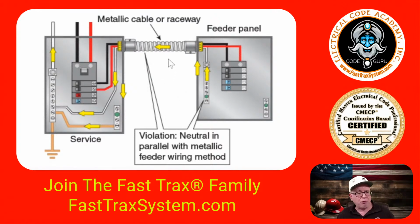So that was the whole purpose of the illustration, not just to talk about the objectionable current, not just to talk about the improper case to neutral, but also what are your recommendations for fixing it? Well, in this case, you could remove this and put an MC cable in there with a properly sized equipment grounding conductor based on the size of the overcurrent protective device.